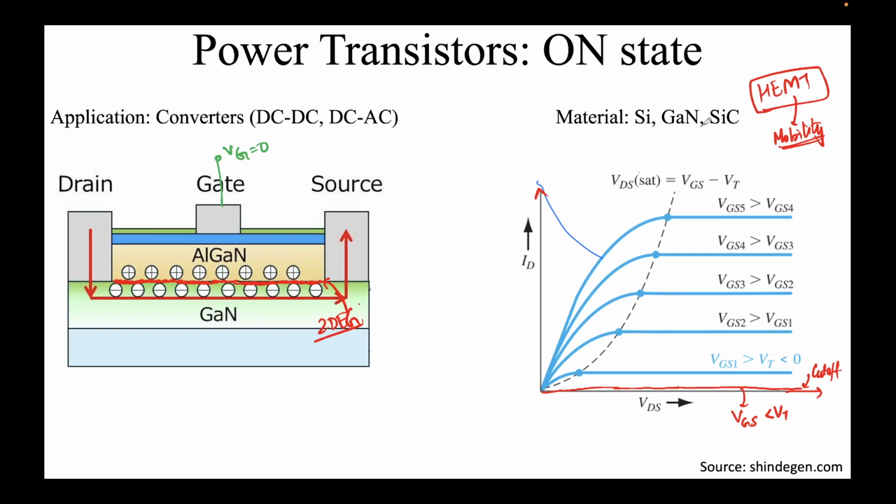It just so happens that the electrons over here are solely inside the gallium nitride, and they form a quantum well. Okay, I cannot go into the details of that. That enhances the mobility of these transistors. Okay. The amount of electrons that are here depends on the thickness of AlGaN and the concentration of aluminum and various other factors.